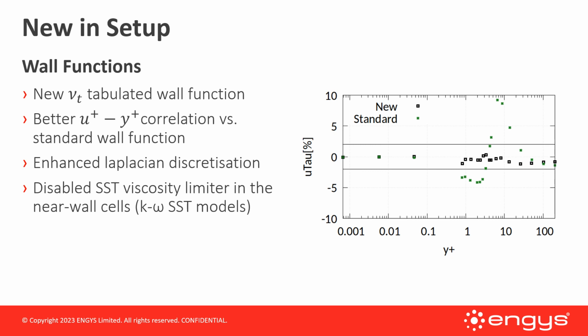the Y plus value. To address the issue of Y plus insensitivity in shear stress computation within CFD and wall functions, a new boundary condition called NUT-U tabulated wall function has been introduced, which interpolates values from low Reynolds solutions to accurately compute U plus and Y plus, while mitigating discrepancies in traditional models. Also, by employing a modified Laplacian discretization, gradient errors in the viscous sublayer are minimized, accounting for omega's specific distribution and increasing the accuracy of the diffusion term in the omega equation.